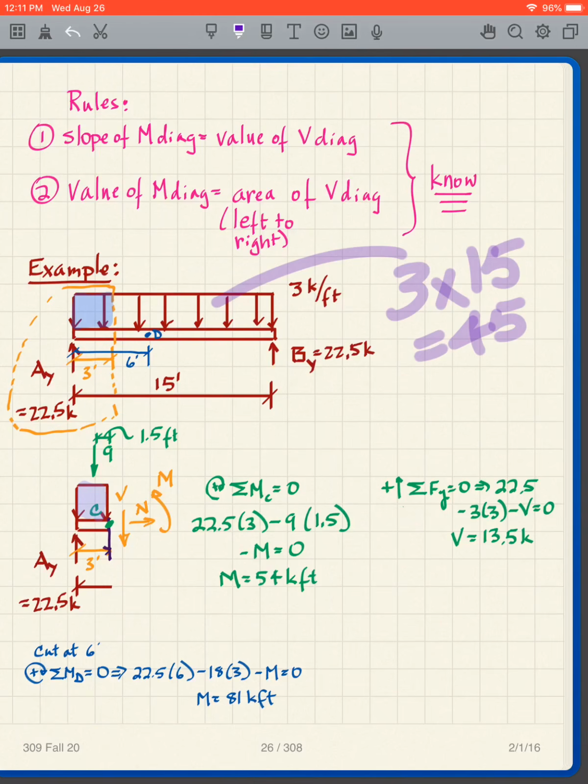Now, I just want to make this comment that in getting the reactions, everything is symmetric and uniform in this problem, and so you should also look for shortcuts as long as you make the shortcuts correct. If the total load is 45 kips and everything's uniform and symmetric, then I can get these reactions very simply.